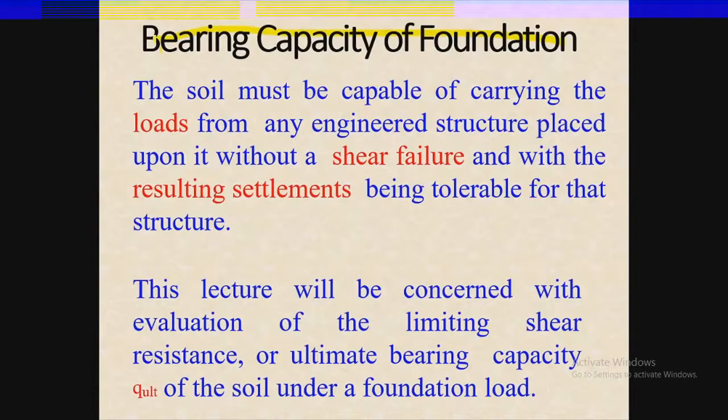As you know, the load of the structure is taken by the foundation, and the foundation then transmits that load of itself and the superstructure to the subsoil safely without causing any shear failures of the soil, and the resulting settlements produced by the foundation in the subsoil must be within the allowable limits.